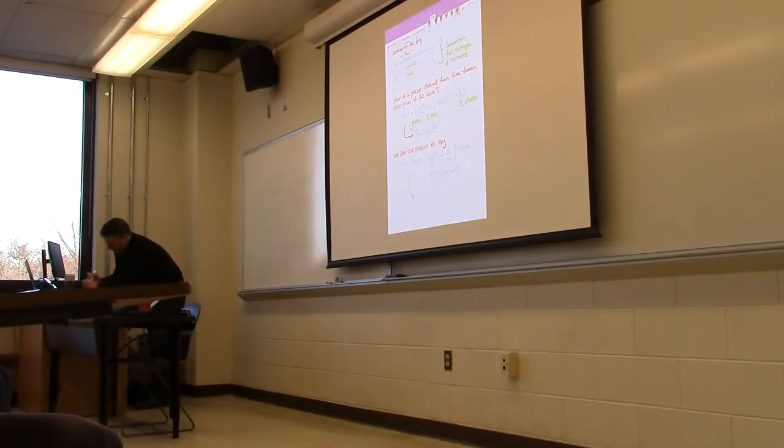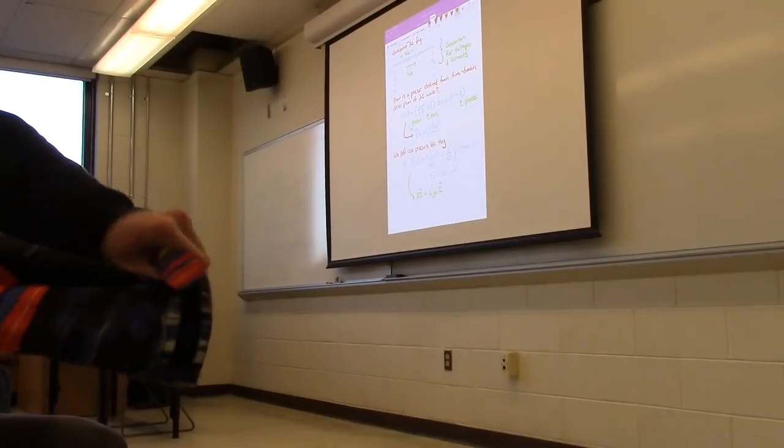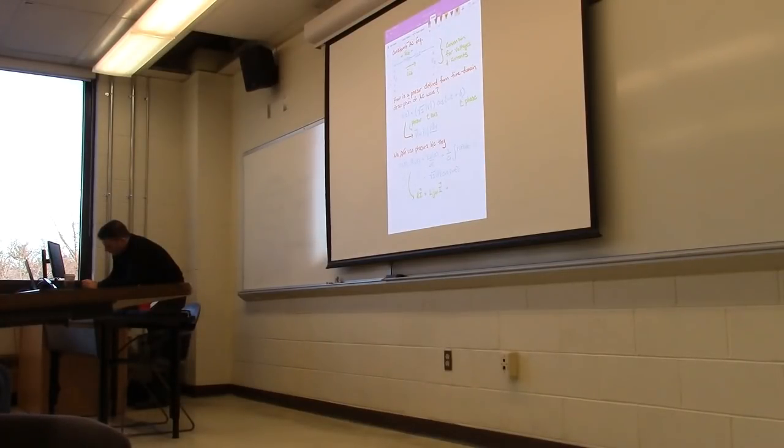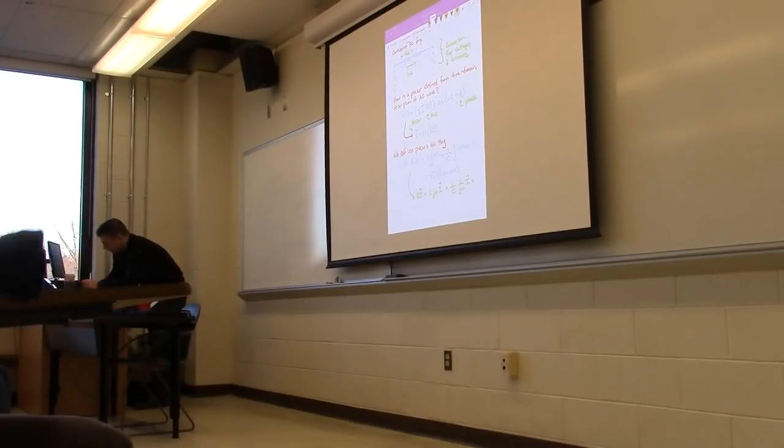So the polar form looks a lot nicer. That's going to be R times a phasor representation of I, plus L j omega phasor representation of I, plus 1 over C, 1 over j omega phasor representation of I, equals V.